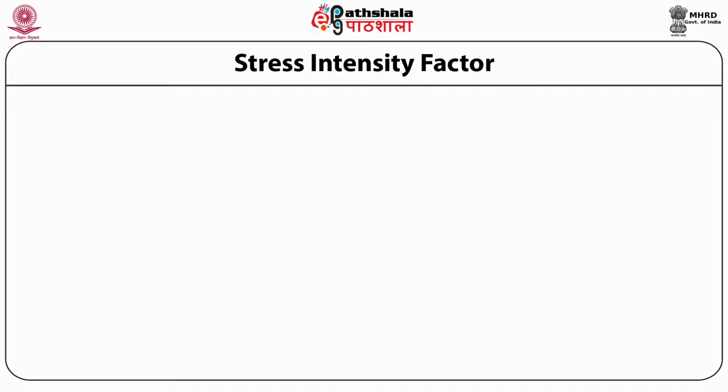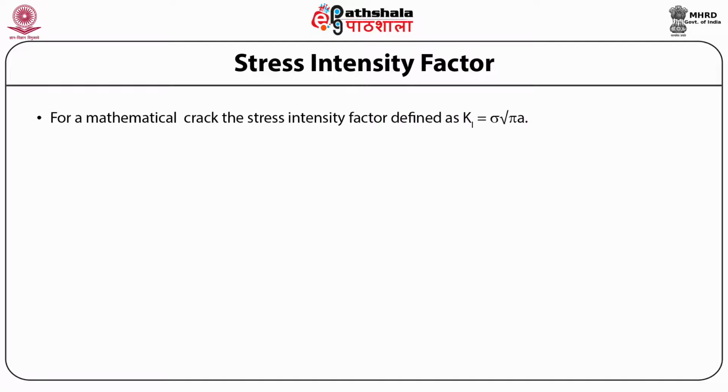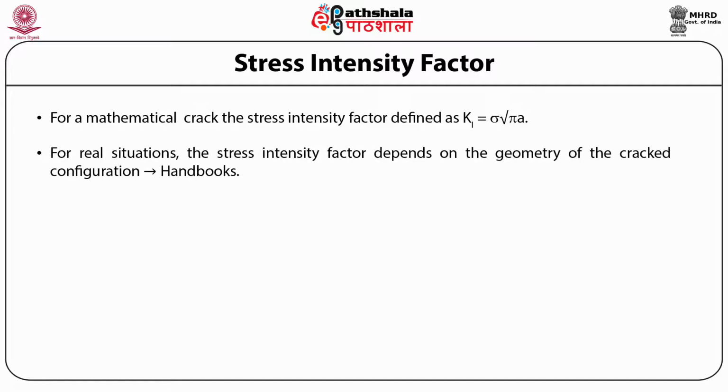Stress intensity factor. For a mathematical crack, the stress intensity factor is defined as Ki equals sigma multiplied by root of pi a, where sigma is the applied stress and a is the half crack length. This was defined for the case of an infinitely sharp mathematical crack. For real situations, the stress intensity factor depends on the geometry of the cracked configuration.